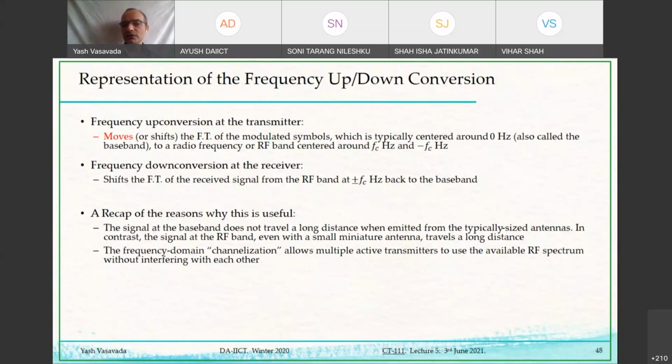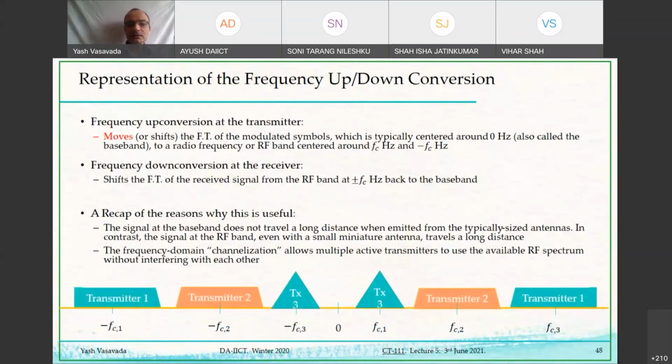You have to keep on tuning your radio to different frequencies, and it will give you different stations, different audio channels. That entire signal is coming to you together. It's frequency division multiplexed. All those different signals are arriving at the radio antenna collectively. And then when you tune the radio to a particular band, it extracts out only the audio signal corresponding to that particular band. It is the modulation which is allowing the FM transmitter to do that, right?